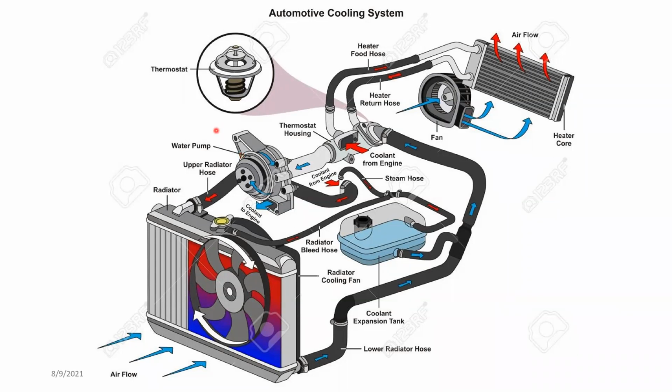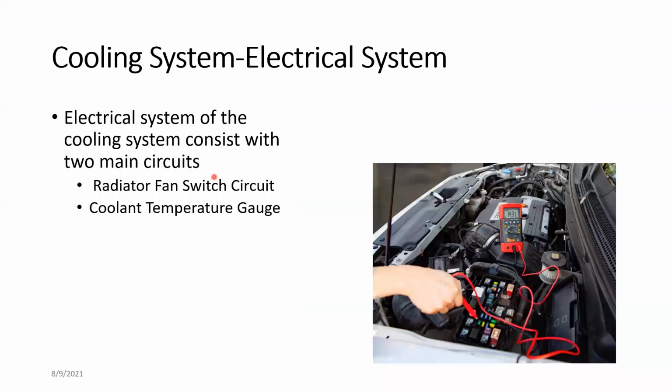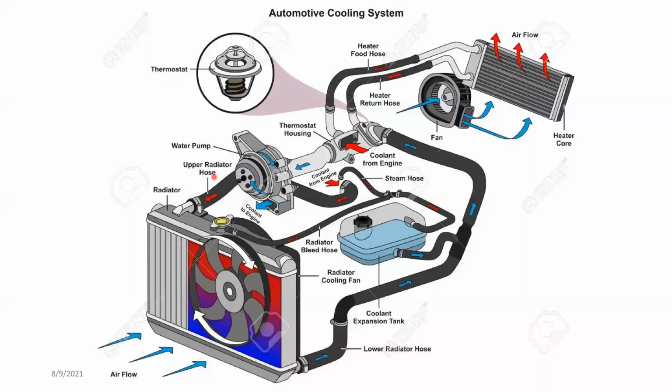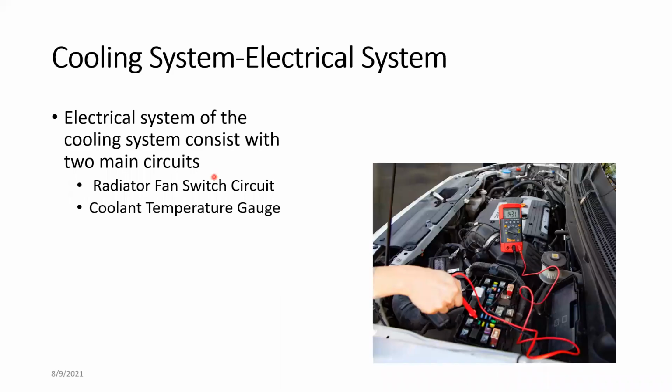By having an electric pump, this can be solved. Also, the engine can work a bit more efficiently, because its power will not be used to run the pump, which is not necessary at all times. Only when necessary will it be driven. We'll discuss this part when we discuss the electric engine management module.